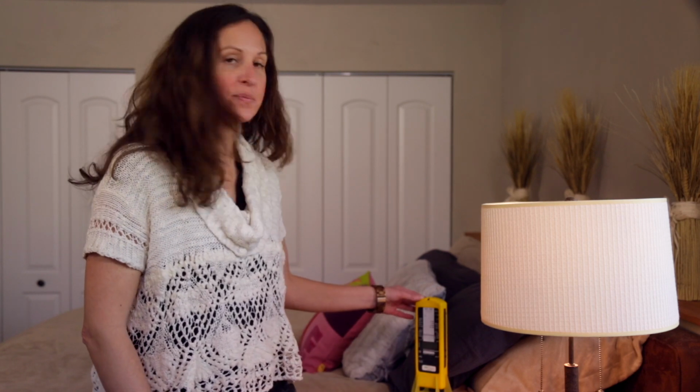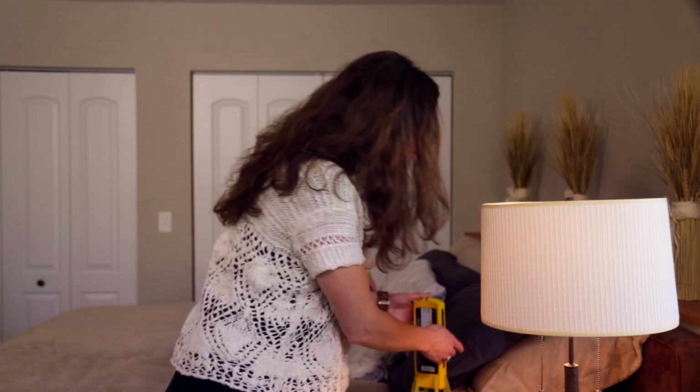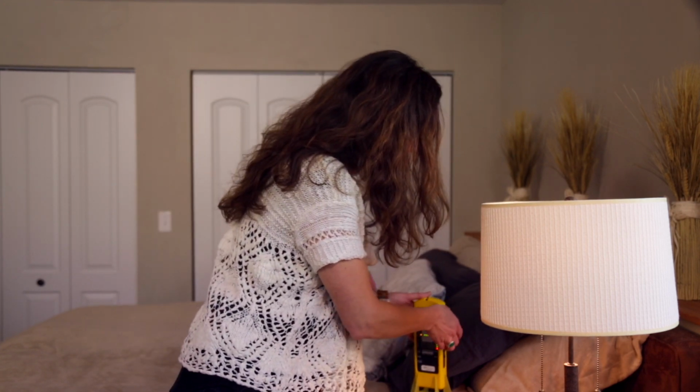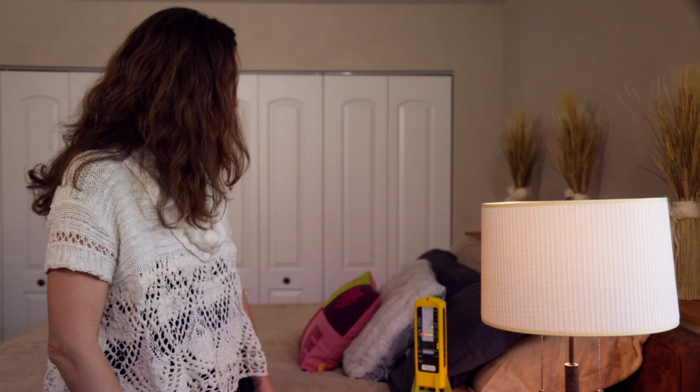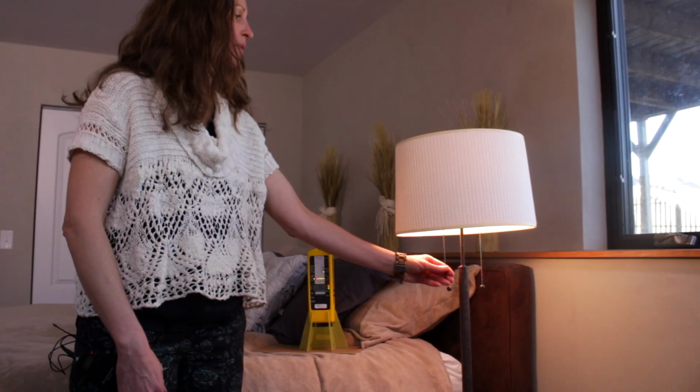This is a 3-axis meter that measures the electric fields that most building biologists will be using. It's called an NFA 1000. When I turn on the meter, it reads approximately 16 volts per meter in the sleeping environment with the lamp on.